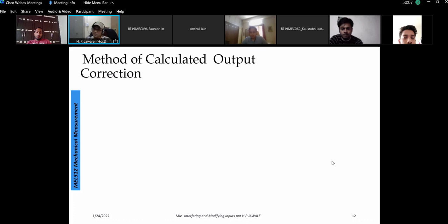So I have a clear difference of 40 degrees, and I know the value of alpha. Using alpha, I can find the expansion equals L alpha into del T. This is a very simple expression that we have studied in mechanics of materials, or solid mechanics. So L alpha del T, alpha is known, del T is 40 degrees Celsius. So I know what will change the length.